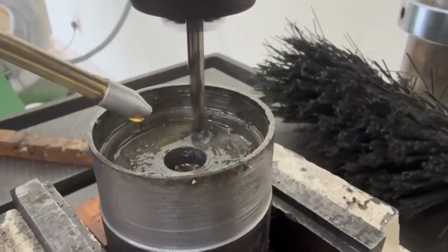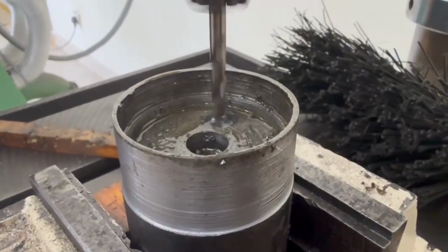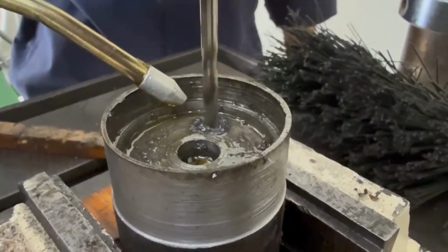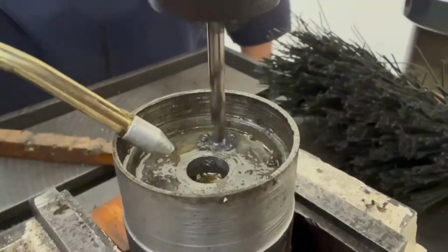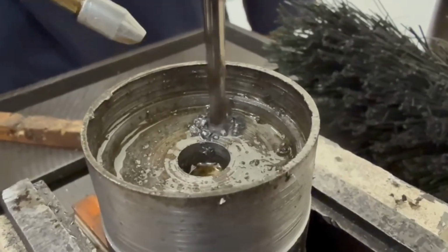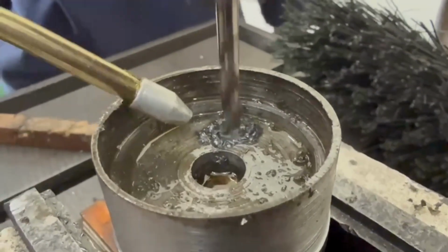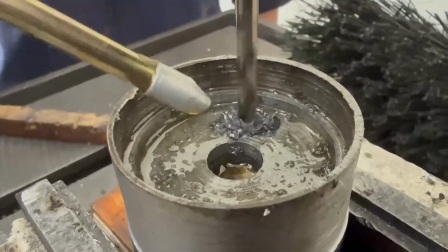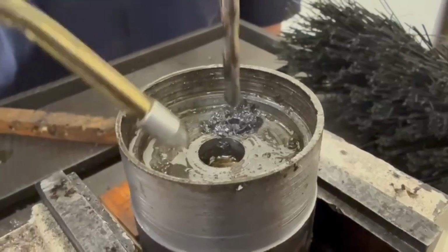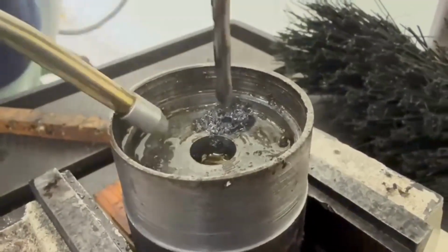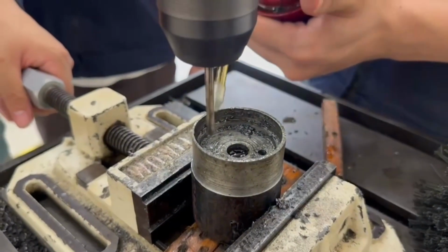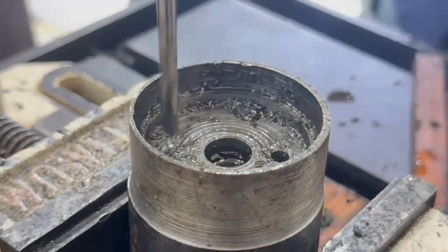This time, the drilling process is executed inside the workpiece. The reason to drill inside the workpiece is to get 2 holes dimensionally accurate for the workpiece. During the drilling process, it is advised to pour some oil on top of the drilling area. The oil is used during drilling to act as a lubricant and coolant. It reduces friction between the drill bit and the material, prevents the bit from overheating, and helps flush away metal shavings. This significantly extends the lifespan of the tool and results in a cleaner hole.